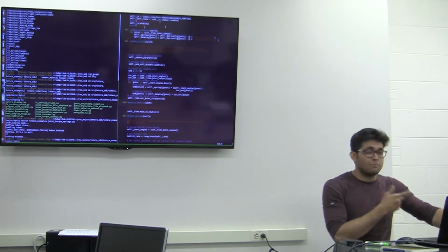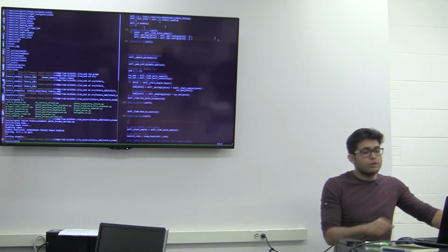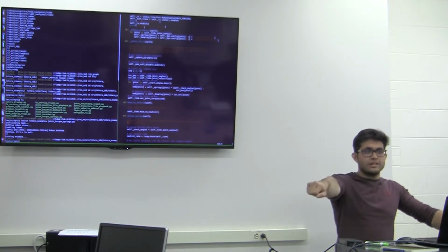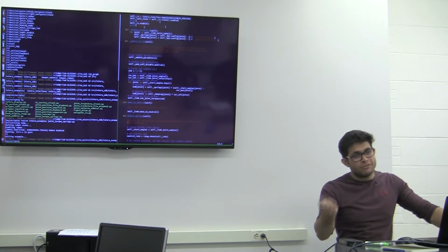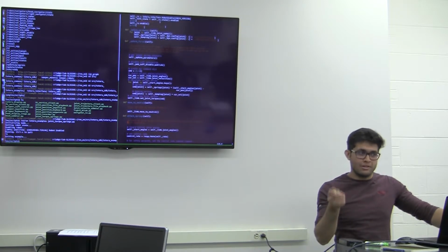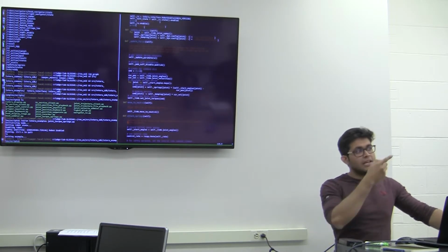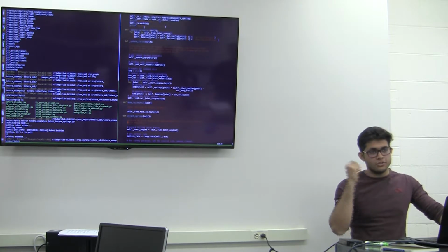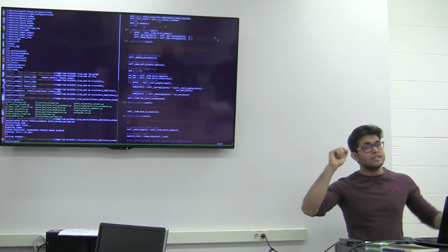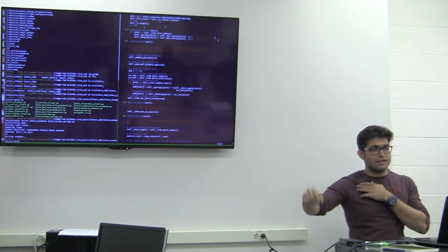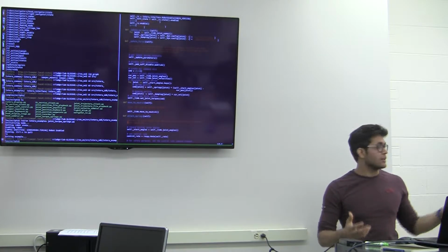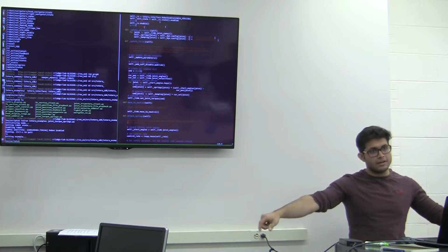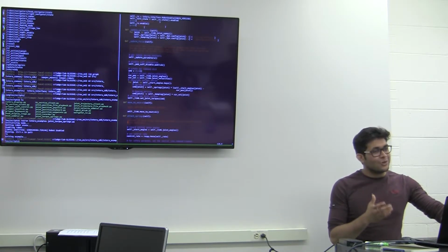But if you try to move it manually, you will get stuck in singularity for sure. If you start publishing one by one, like 10 degrees, 10 degrees, 10 degrees, and move it to a singularity position, don't try this, because we have to reconfigure the robot again. That's what we have to do every time the robot gets stuck in singularity. Even with KUKA, we have a default function that if it's in singularity, it runs all the joints again. Basically, it moves each joint one by one to get out of that singularity and calibrates it again. It's the same thing with this. There is a calibration function that we can call, and it has to calibrate again. So don't try to go into singularity.